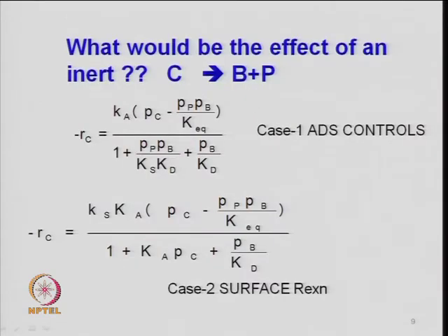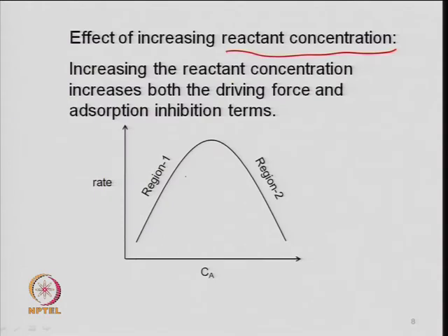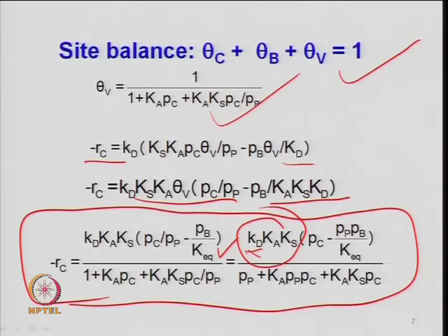That is because of the terms shown here in the earlier section, if I look at the effect of partial pressure of each species. So, increase the partial pressure of C; initially the rate will increase, depending upon the contribution of P p and P c, and accordingly the rate will change. Because during the reaction, if you have an integral reactor or a commercial reactor, P p, propylene, is also forming, right. So you can see here that it may hinder the rate of reaction.